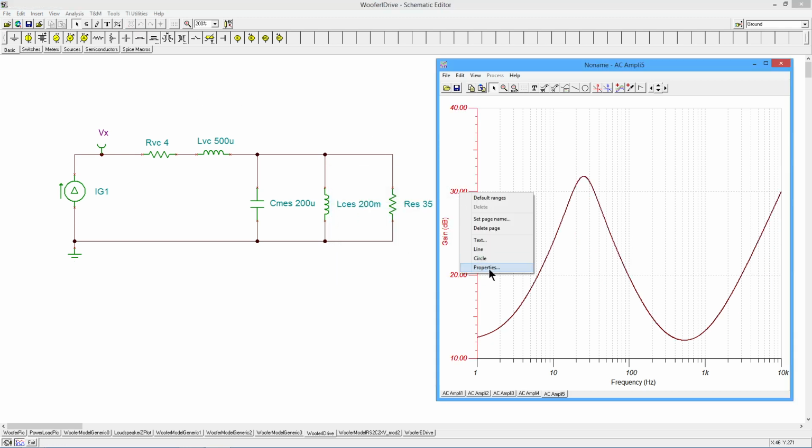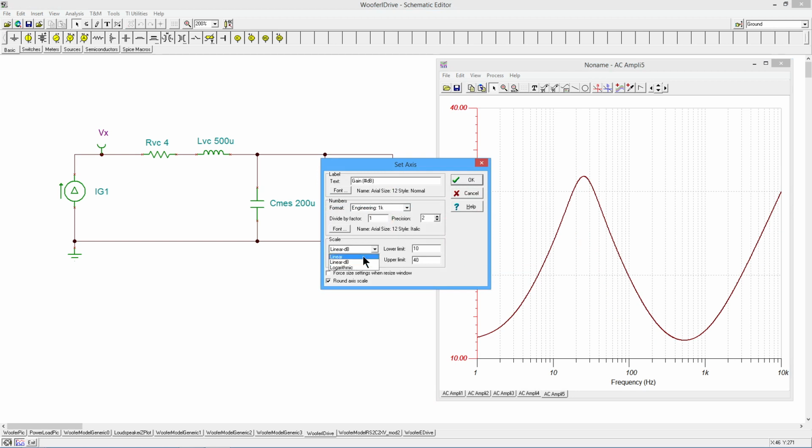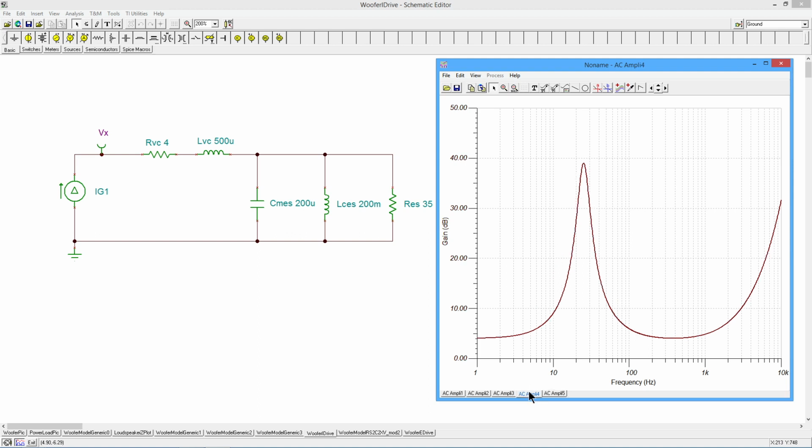All righty. And just to compare everything on an even keel, let's go back and forth, right? So here's where we started. And then what I did is I dropped the C value and increased the L value, which, as I said, should give us a fatter response curve, in other words, a lower Q. And that's exactly what we see. That peak has not changed. This up here hasn't changed. This down here hasn't really changed. How we get there, of course, has.